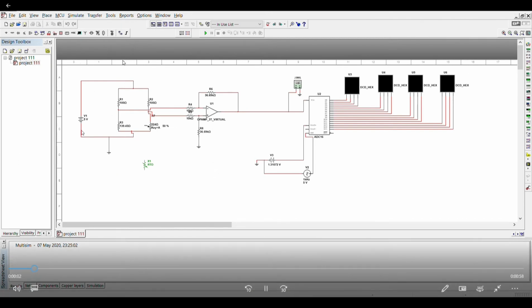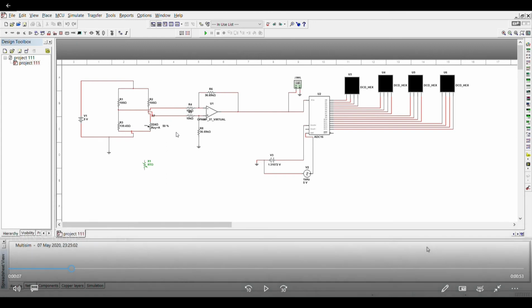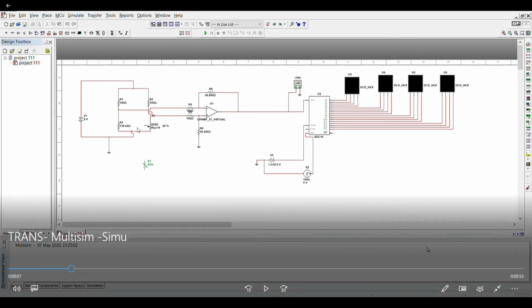As we can see here, we have V source equals 5 volt, R1 equals R2 equals 100 ohm, R3 equals 139.43 ohm. R1, R2 and R3 are constant. We have R4, which is the resistance of the sensor, which will vary between 139.43 ohm to 224 ohm.